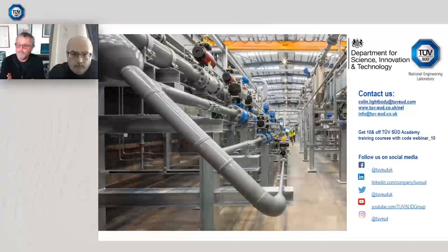And one that I know from talking to my colleague, Dr. Chris Mills, here at TÜV SÜD, one of the world's leading authorities, if you like, in Coriolis meters, zeroing the meter. If you don't zero the Coriolis meter properly, it will not work as well as it should do. So installation problems, two-phase flow, and zeroing of the meter, I would say, are the main things that will impact the performance.